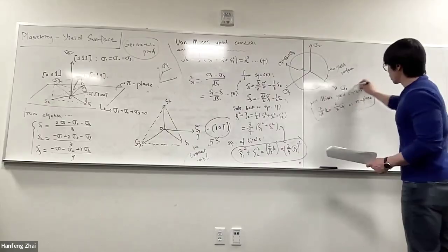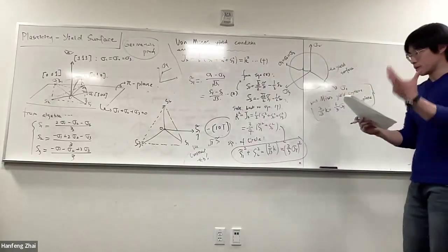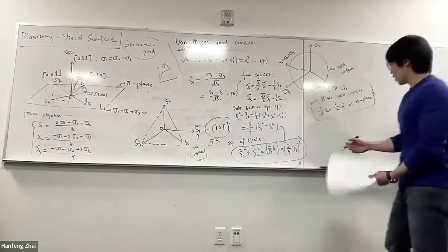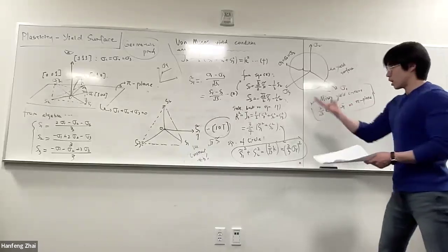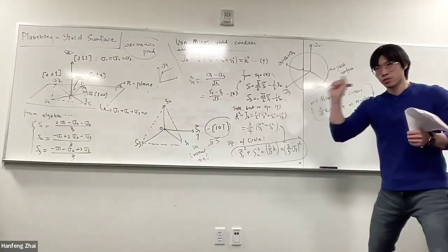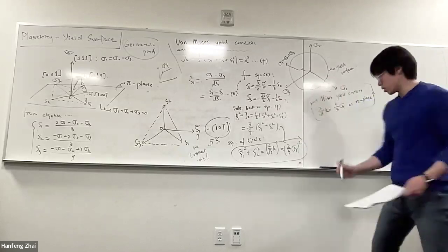This is an important conclusion we obtain just by doing mathematical geometric analysis. And we can then define the yield surface much more accurately or precisely. On the pi plane, the 3 axes that are being projected on the plane are the 3 principal deviatoric stress components, which is S1, S2, and S3.